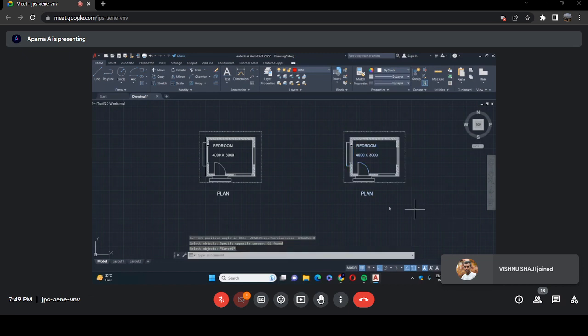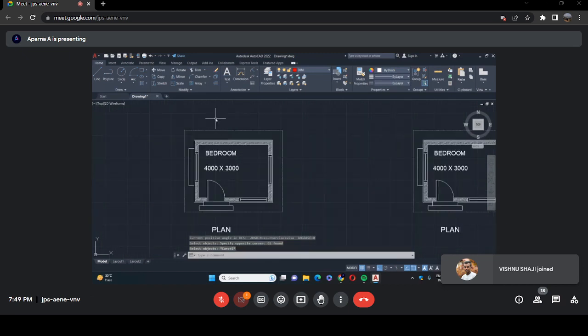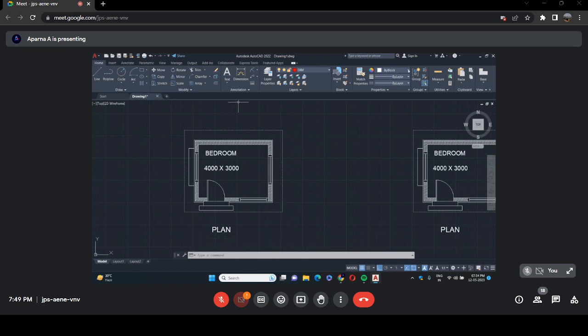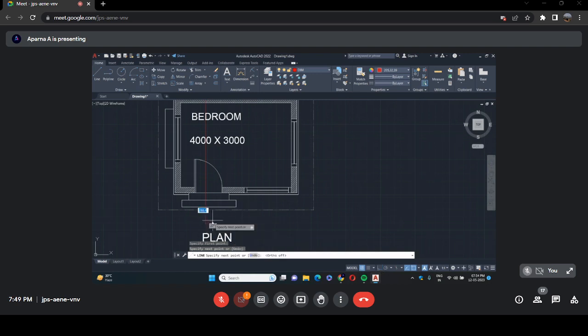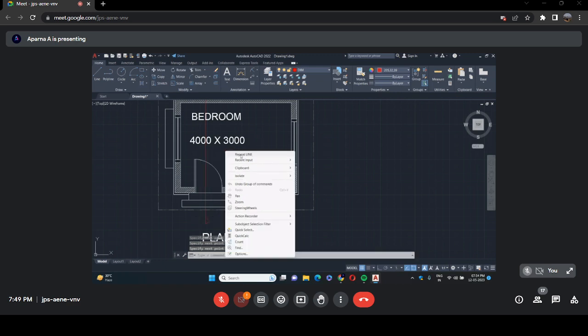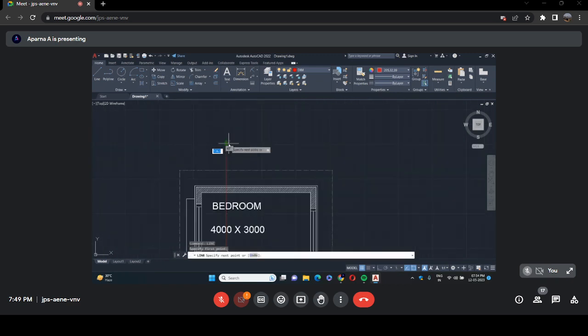Before rotating, I am planning to cut it through the door, so I can draw the cutting line and show it in another color line, cutting it through here. I'm looking to the right, so I can draw arrows towards the right, and I can hatch it. Hatch.